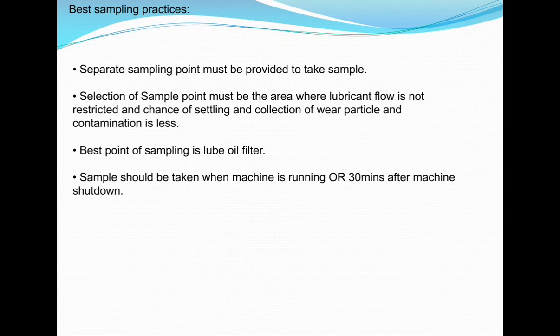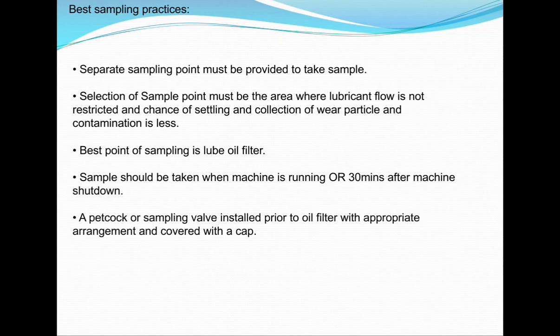And the point from where we are taking the sample must be properly blocked or properly dummied by using petcocks or valves, because that dummy is used to prevent oil contamination, as well as prevent leakage of oil after taking the sample.